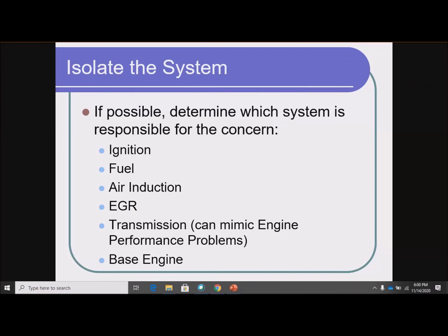I was saying that one of the systems, something's not happening right. Intake's not happening right, compression's not happening right. So what are the problems here, right? If I've got a cylinder misfire, is it a compression problem? It could be. How can I tell the difference? If it only misfires on acceleration, for example, it's probably not a compression problem.